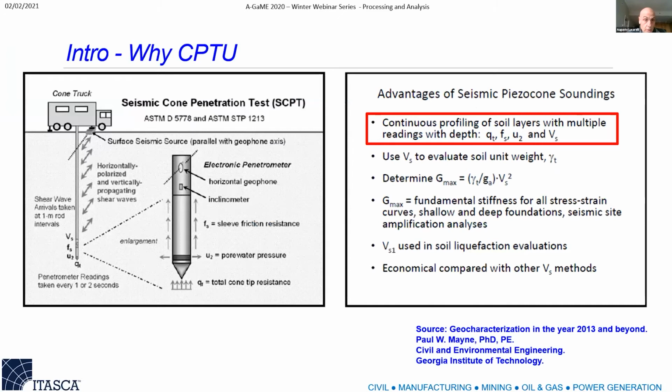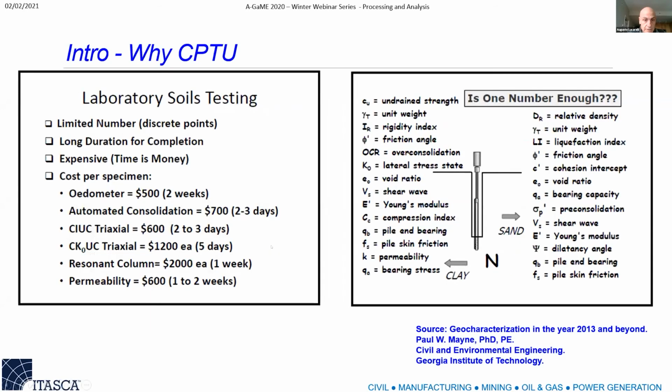Why CPTU, or possibly, preferably, seismic CPTU? Essentially because we can get many more data in a continuous way, and we can interpret many soil properties that are useful to profiling, consolidation, stiffness, in particular when you're doing a deformation analysis. The traditional way of determining the soil stiffness may not be representative of the volume that you are engaging in the project. So you get much more information in essence. Whenever there is the chance, CPTU is a definitely interesting tool to implement.